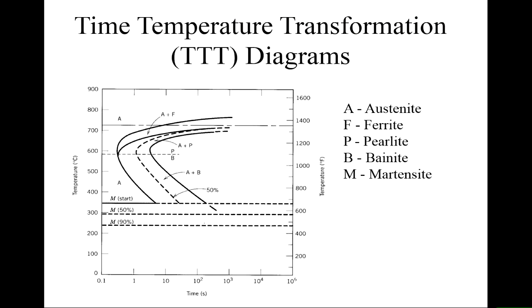Okay, so I finished the last lecture talking a little bit about the fact that although the structure of steel directed by thermodynamics is fairly well defined by the phase diagram, in real systems we have to take into consideration the cooling rates, because these transformations don't take place immediately.